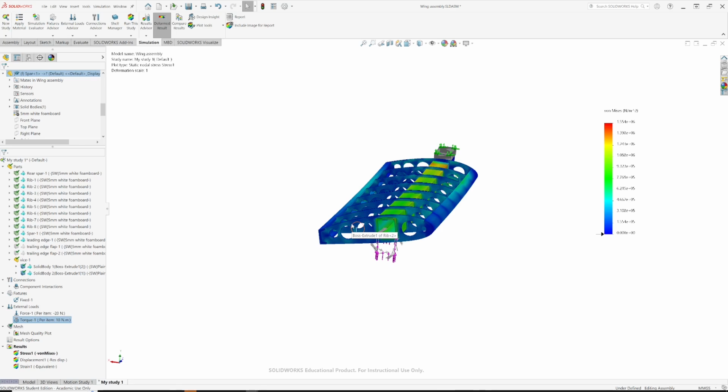So you're now equipped to do the full design process for a wing spar and associated secondary structure. You can do conceptual design using simple theory in Excel. You can draw your wing up using CAD, making parts. You can make an assembly, and then from this assembly we can do some structural analysis and compare that back to what we predicted from Excel. And then from this, hopefully you can work towards making a wing spar that meets all the requirements, but it's the minimum mass of material used to do so.